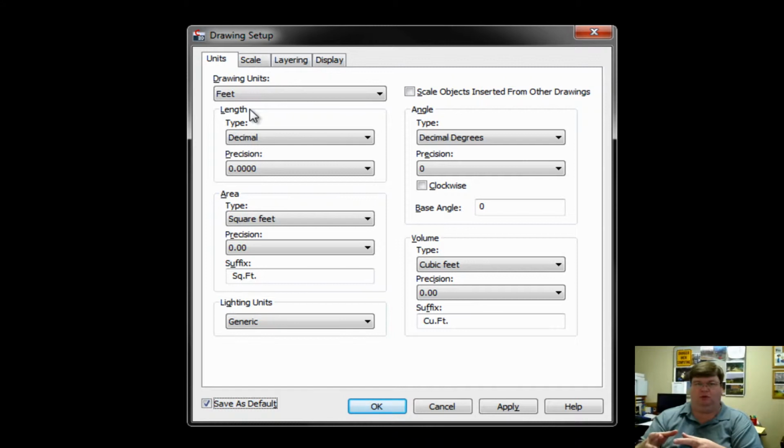We think that's preferable to dealing with the scaling and having to touch every old drawing, and we may find out that that's wrong, but right now that's the way that we're going to go with it. So we're not going to have AutoCAD automatically scale things. We'll handle the scale ourselves. The other thing that we're going to do is set it up to where the user for this workstation doesn't have to fool with it again.